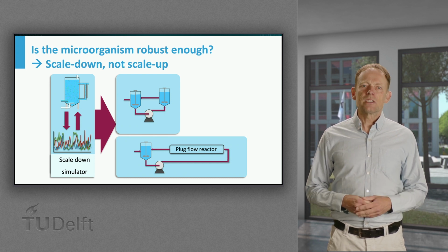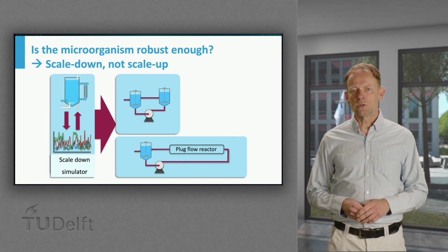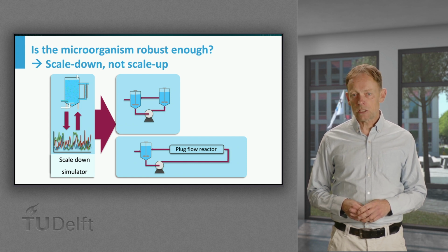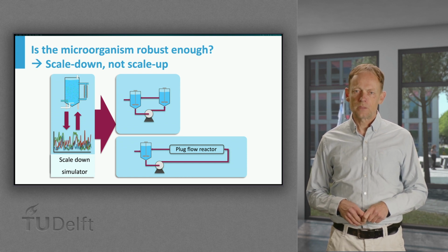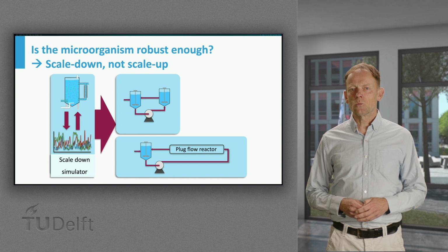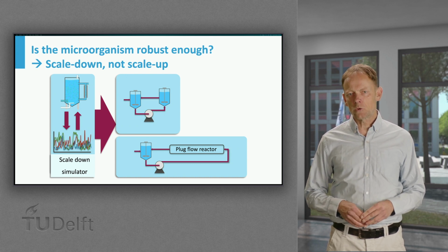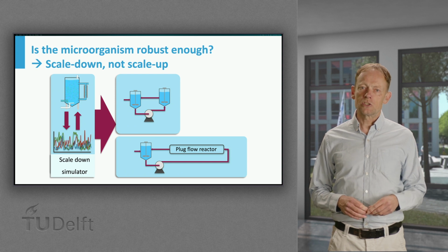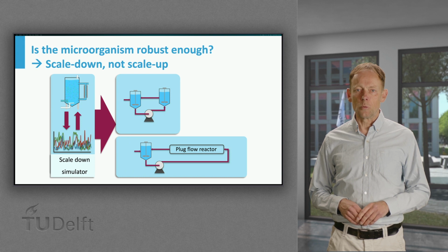On the positive side, this probes the performance of the culture in which cells get different exposures to the conditions: fast changes, slow changes, and also with smaller and bigger amplitudes. However, a downside is that one needs pumps and recycle loops, which is complex to execute and could bring artifacts, such as shear damage by the action of the pump or nutrient depletion in the loop.